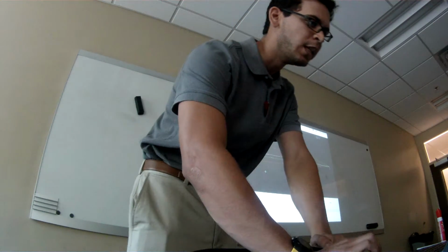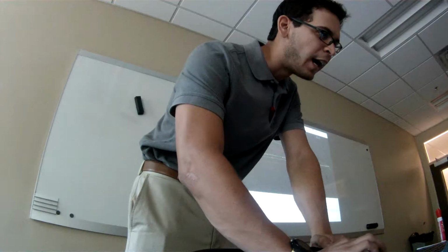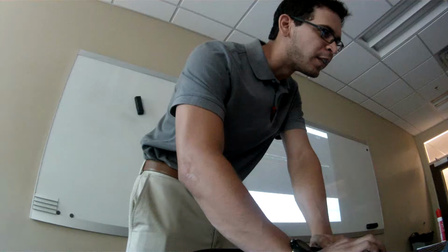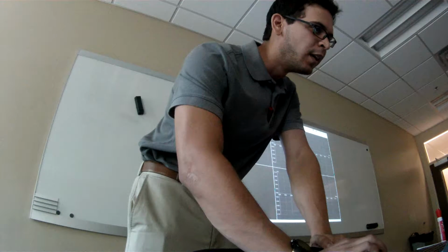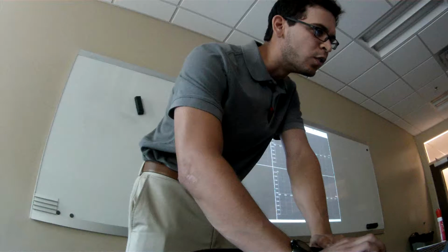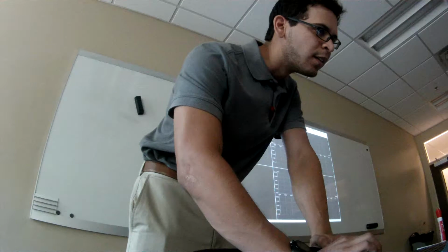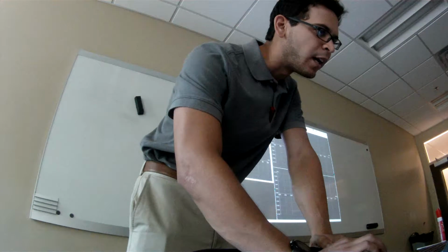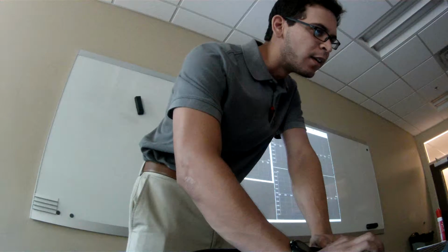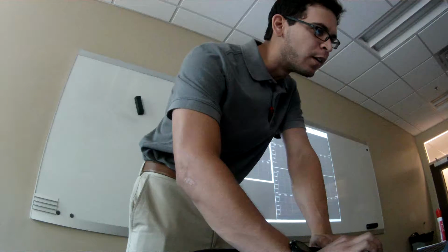All right. So then from here, you can go to File, and then I think this is XFoil Direct Analysis. And then you can go to Analysis. Is it Batch Analysis? Yeah, Batch Analysis, Foil List. I'm going to select both of my airfoils.